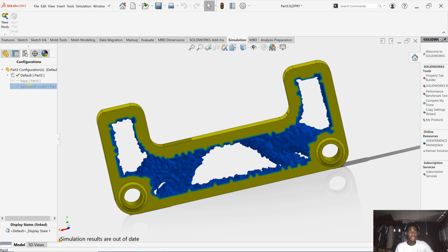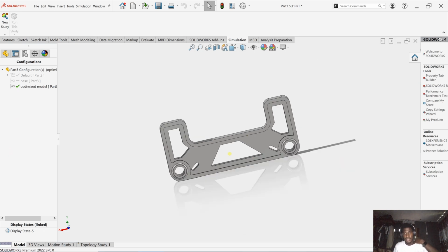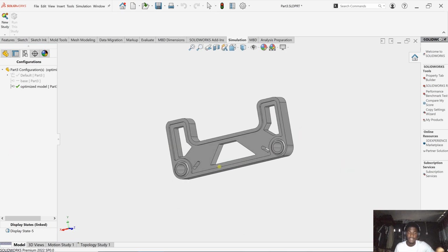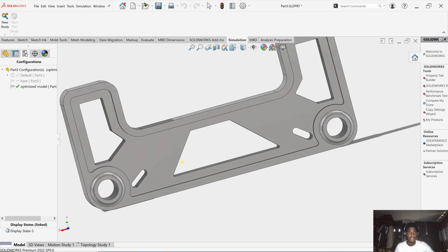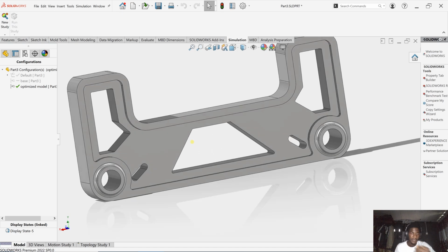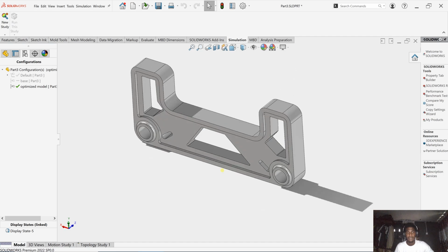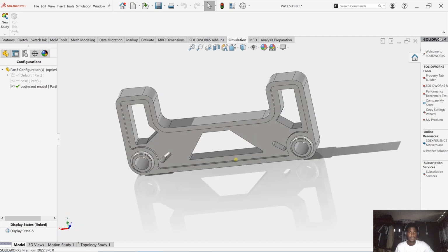I like cutting it this way because if I send this over to a manufacturer and he complains that some places are too small, or other things, I can just manually go and increase the fillet or whatever. So it gives me full control of how I want these slots or these holes to be.